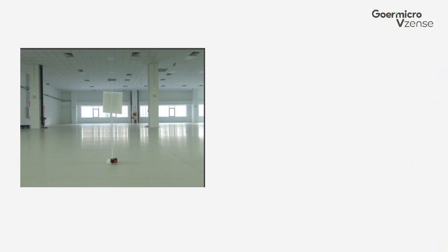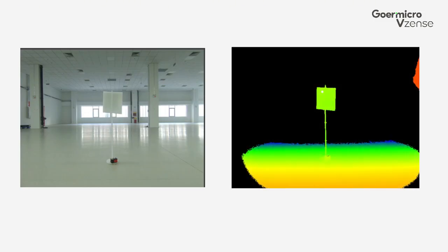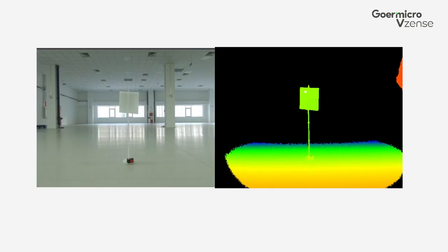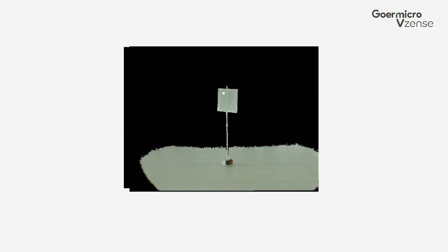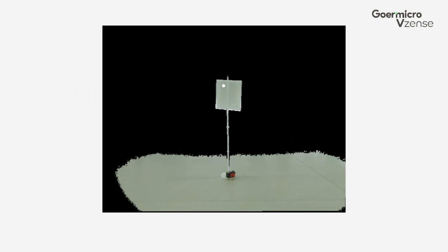For example, in the RGB image shown, the white target is the object of interest, but its color closely resembles the background, making annotation and recognition labor and compute-intensive. However, the depth map reveals the target's distance within the working range while filtering out the distant background. Using RGBD data, we can precisely segment the target while discarding irrelevant background, drastically reducing processor workload.